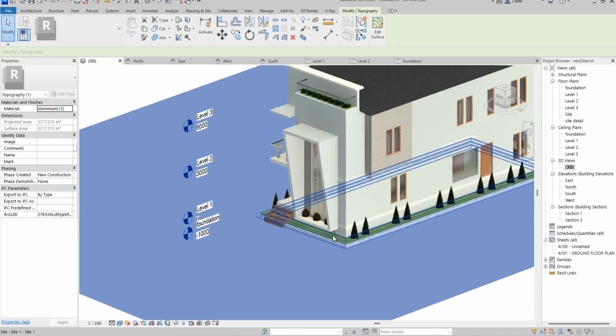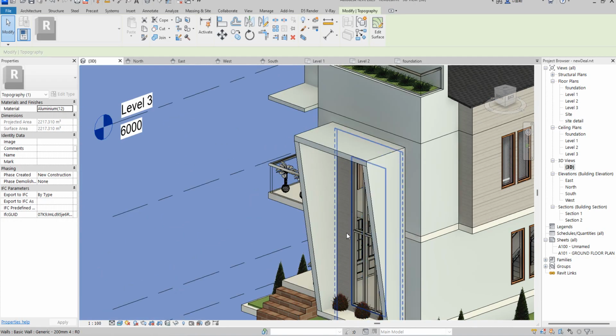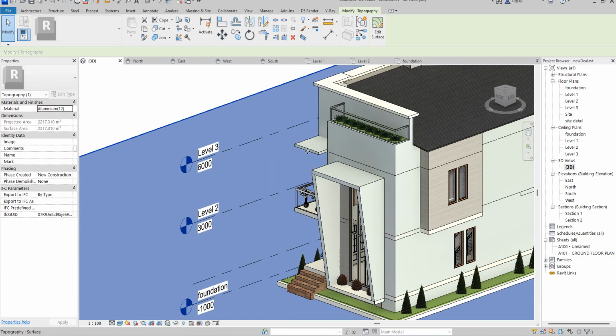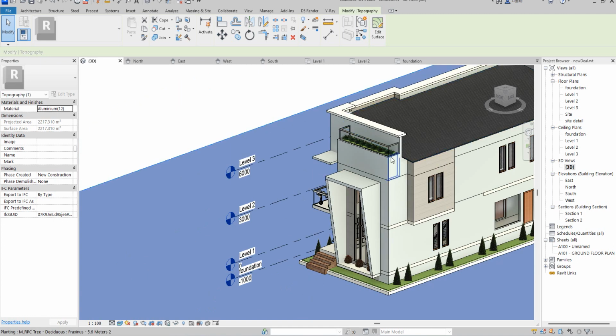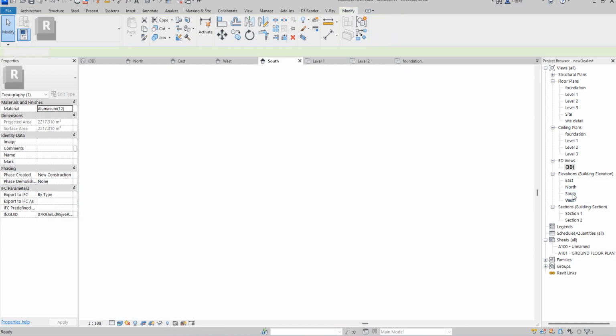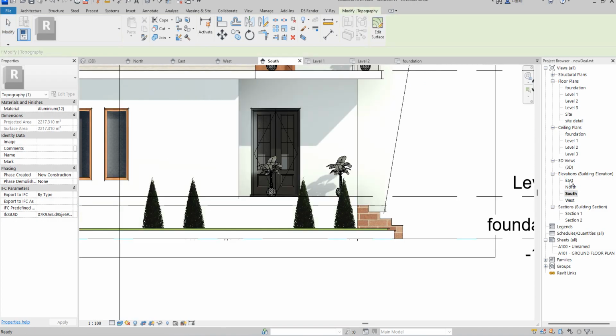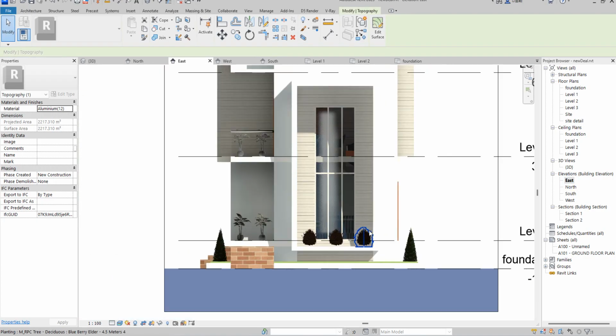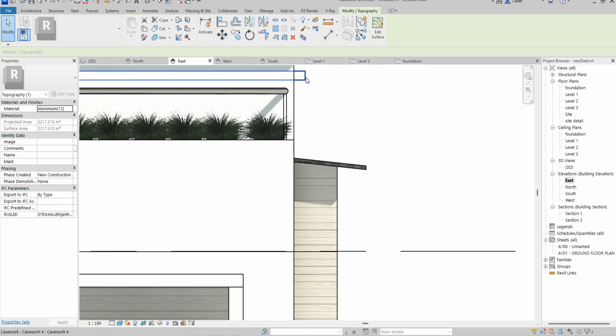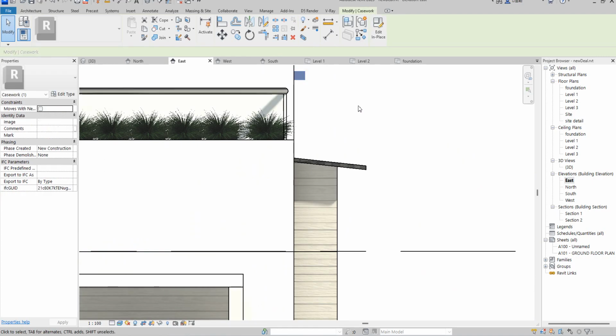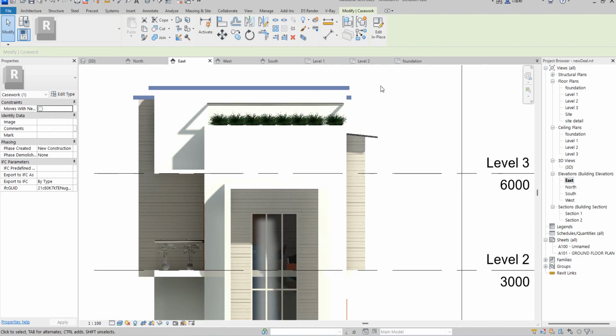The next thing I need to work on is the color composition surrounding it and some of the labeling aspect and design. The first thing, let me quickly do the facia concerning this. I'm going to go to elevation, front elevation. What I need now is to go to component, or choose model in place editing.